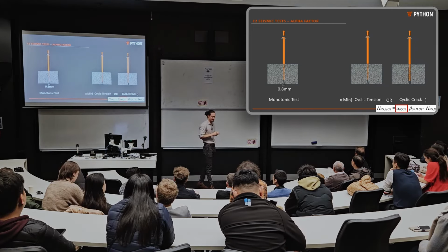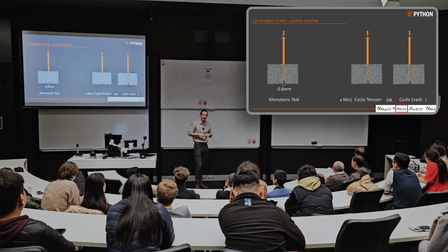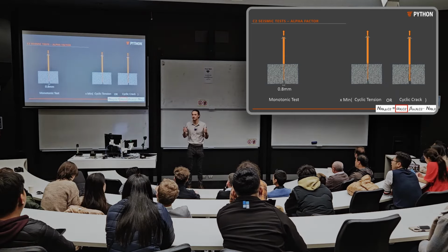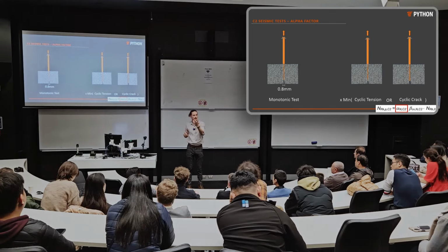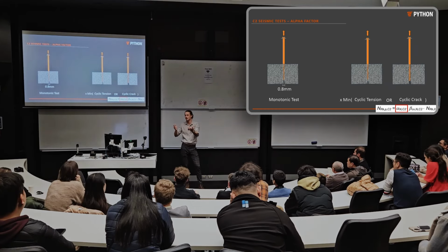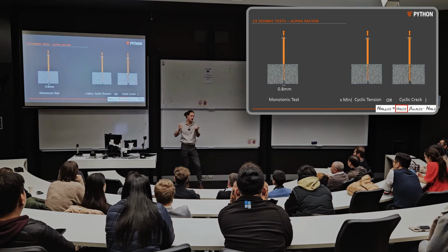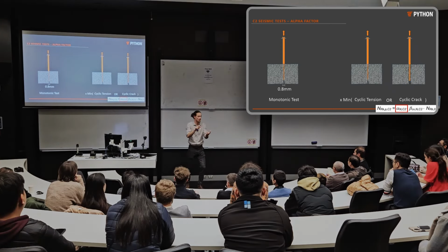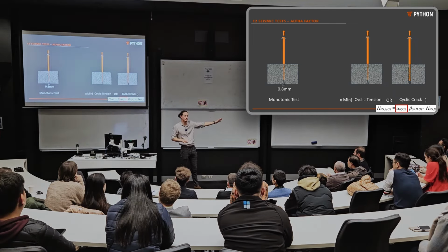The reason is there's another study done in the early 2000s where they built a single degree of freedom reinforced concrete moment frame. They mounted some anchors to the underside. They measured the tension load in the anchor over time, and they measured the width of the crack over time. They put it through thousands of cycles. The conclusion of that study was basically that there is no statistically significant relationship between the max tension load in the anchor and the max crack width. Don't worry if you didn't digest that entirely. The thing to take away is that it makes sense and there's justification for it.